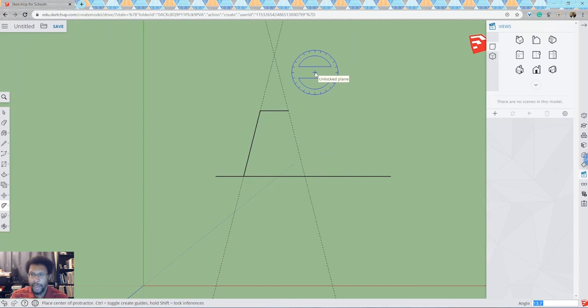So I'm going to hit escape now, and I should be able to move around freely. I'll go back to the line tool, and what we'll do now is go over that dashed line. Basically it will be the same angle on the left and the right hand side. Then, just like what we did in one of the earlier lessons, I'm going to drag it along with this black line right here and type in the number 20 and hit enter. Now this length right here is the same length as over here. Then you can hit escape.